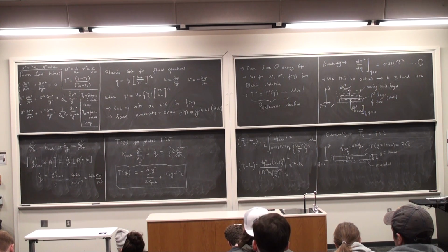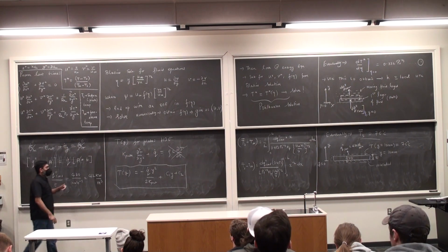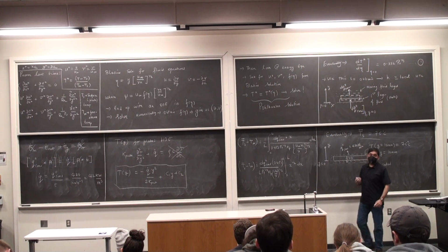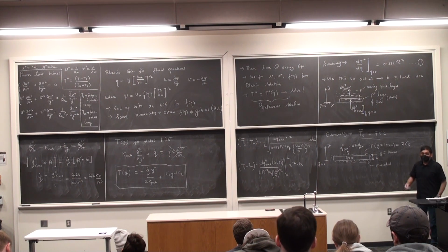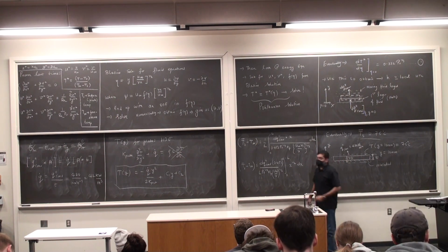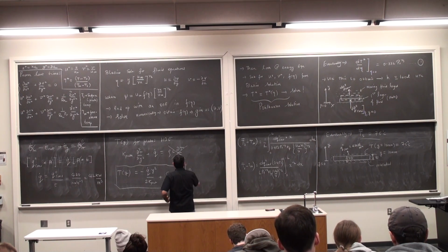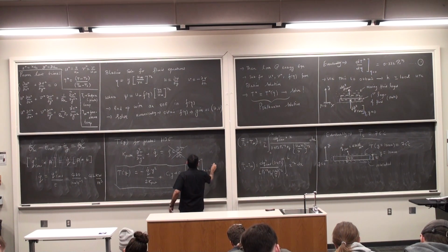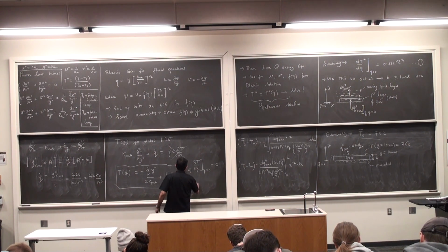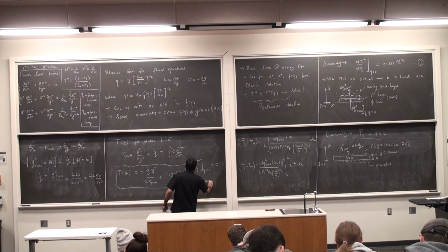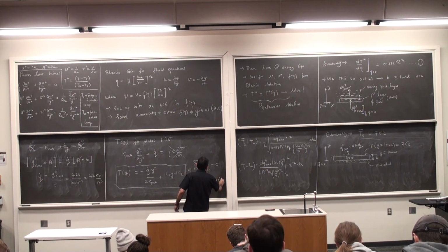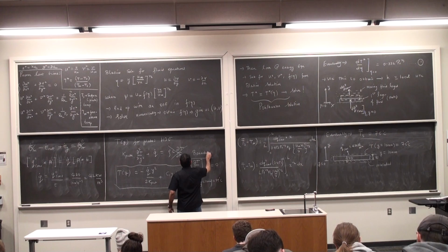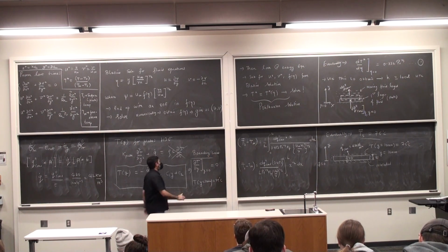I need two boundary conditions for C1 and C2. And I have two boundary conditions. Temperature at the surface of the plate, y is equal to 10 millimeters, is 75 degrees, which is why we calculated that in the first place. Then I say that the bottom is insulated, so dT by dy is 0. So in this case, dT by dy is 0, and T at y equal to 10 mm is 75 degrees. These are the boundary conditions.